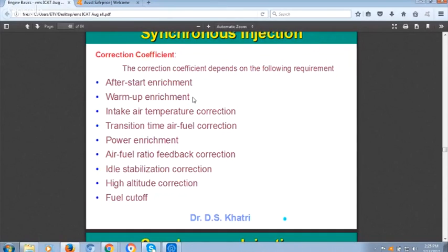One question. Sir, at the time of starting, consider I have shut down my engine and the piston is at bottom dead center. But now I am starting the engine. How will the process take place? There is a crank position sensor. So as soon as you rotate the engine, the ECU will get the indication when the TDC will come. It will take some time to detect the TDC. That is in microseconds.